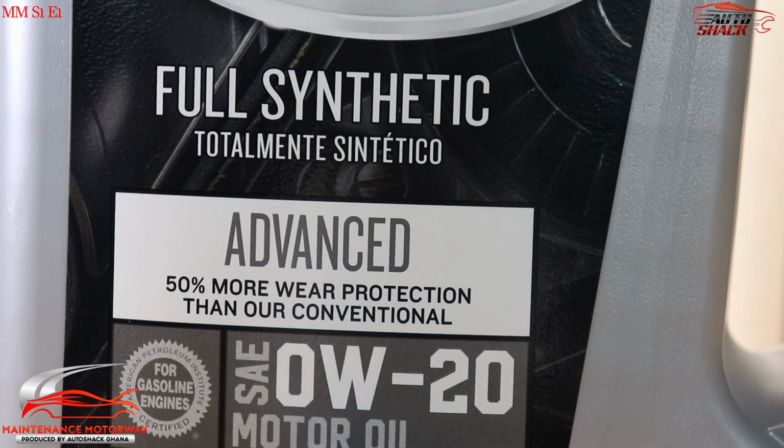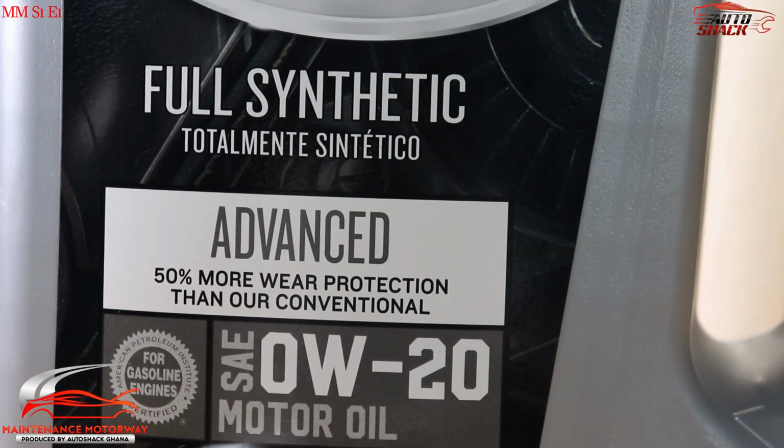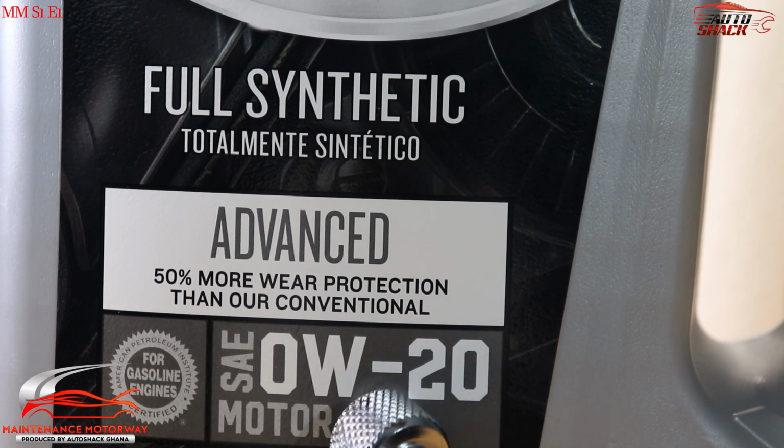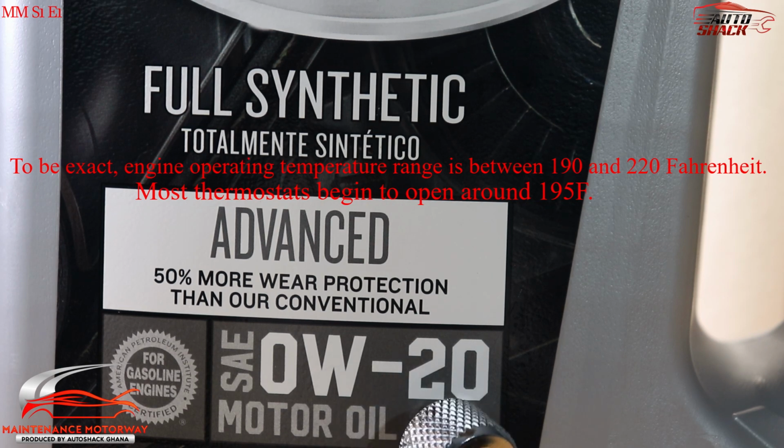Now let's talk about this multi-grade viscosity oil. Because vehicles have to operate in both cold weather and at engine operating temperature, the oils that manufacturers prescribe for their vehicles should have the ability to change viscosities based on operating conditions, especially temperature. The 0W20 basically means zero winter. The W stands for winter, and this 20 is the viscosity at the operating temperature of the engine, which is around 100 degrees Celsius or 212 Fahrenheit.